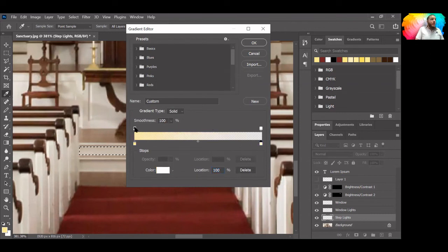Now, up here, I have opacity options, and you can also change where the gradient is located, but we're keeping it simple for right now. So I'll set the top of the gradient to 75% opacity, fading out to nothing, right? So this will show the gradient of light underneath that stair step.